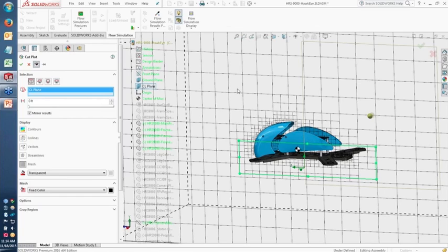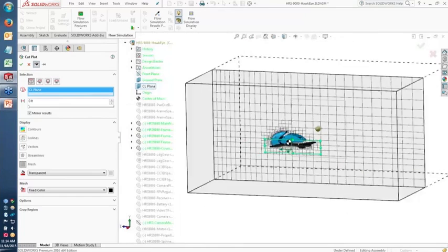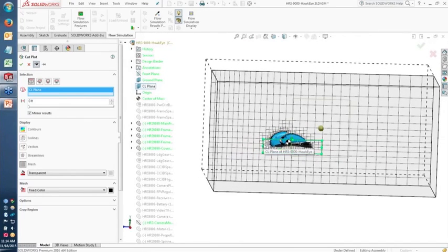And so this new option called equidistant meshing makes it easy to instead just pick some faces on your model and select that you want the mesh to just be refined in a number of zones, sort of a certain distance away from those faces.